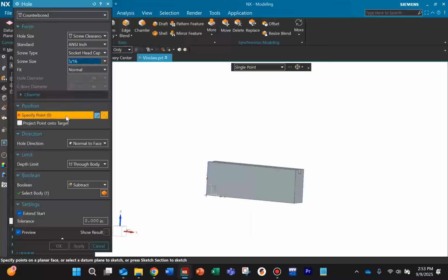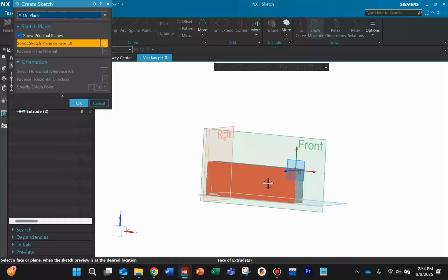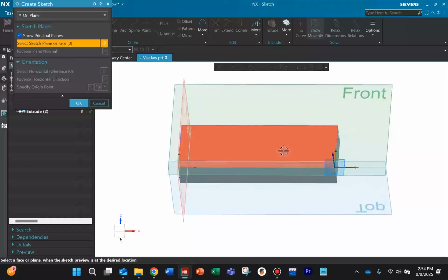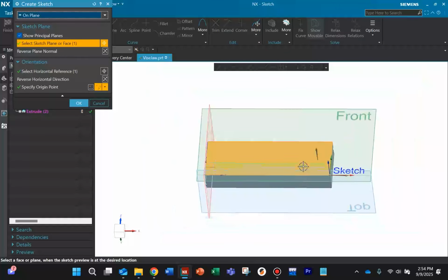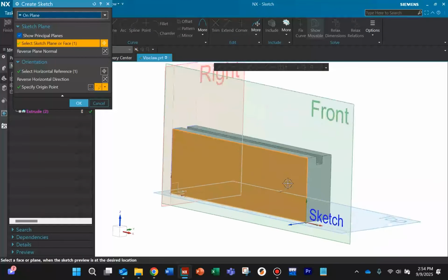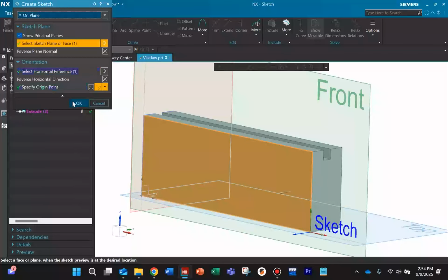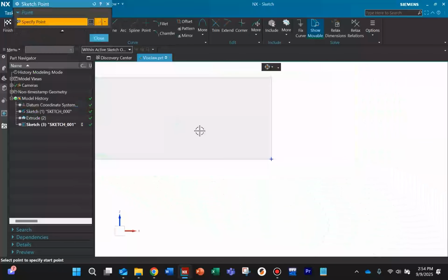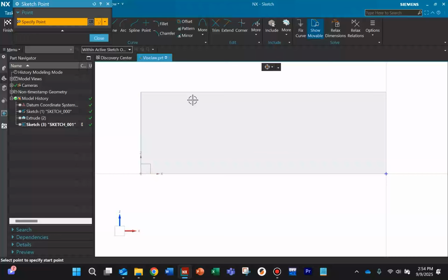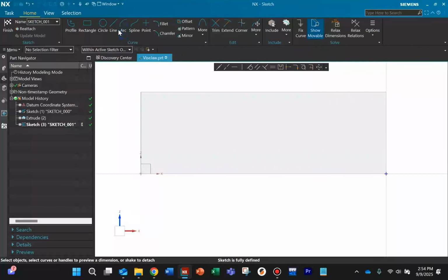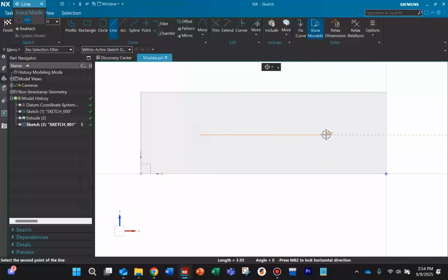So when I go to place my points, for the position, we will go to sketch section. And we're just going to place our points on the face of the jaw, this face here. And I'll say OK. And we're not going to just place down 2 points here. What I'm going to actually do is draw a line. So I use my line tool, draw a line.